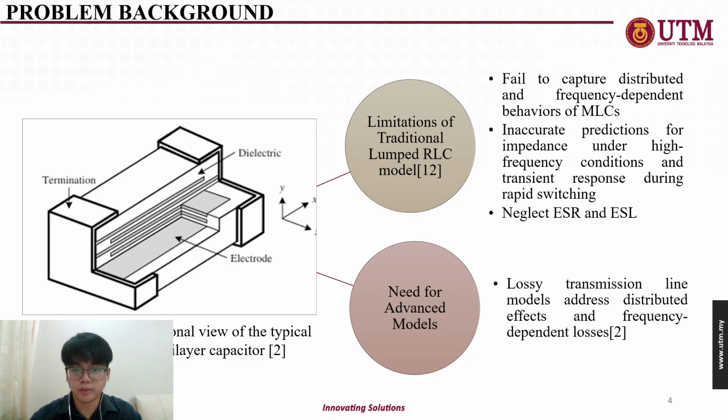So going to the problem background, we're talking about the limitation of traditional lumped RLC models. Traditional models fail to capture the distributed and frequency dependent behavior of MLC, and also provide inaccurate predictions for high impedance under high frequency conditions and transient response during rapid switching, and they neglect equivalent series resistance and equivalent series inductance. So this brings the need for an advanced model, where lossy transmission line models address distributed effects and frequency dependent losses.